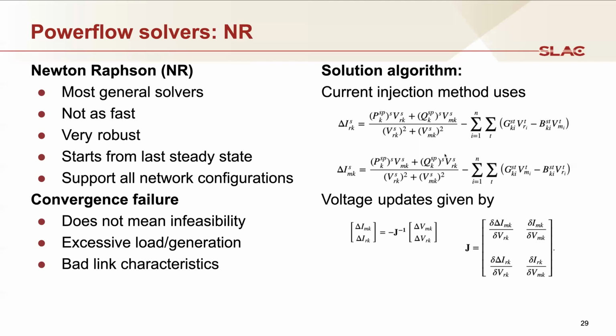It's just that the iteration method and the overall algorithm may come up short given the properties that we've provided in the model. So it is not uncommon to see convergence failures, and the methods for dealing with them are fairly typical. Look at the voltages, look at the currents, and try to identify which node or which link is causing the difficulty for the numerical method, or there may be more than one, and correct that one.